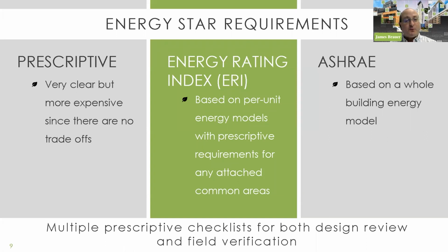The next pathway to identify is the Energy Rating Index. Many of you might be familiar with the HERS rating system. The Energy Rating Index builds upon the HERS raters and organization to be able to do a per unit energy model with some prescriptive requirements for any attached common spaces. Lastly, there is an ASHRAE pathway that utilizes a whole building energy model. Our recommended pathway for people will be the Energy Rating Index due to some of the trade-offs, some of the simplicities of the process, and again, with some of the standard product types that we see being built today.